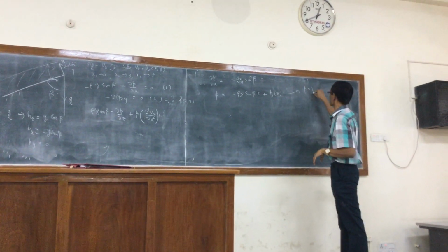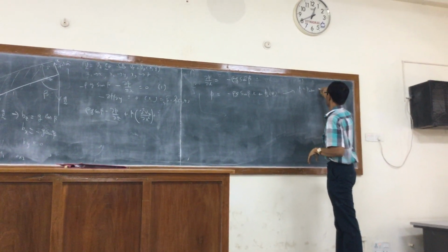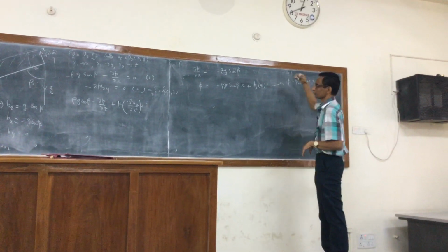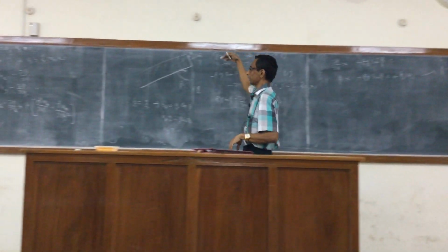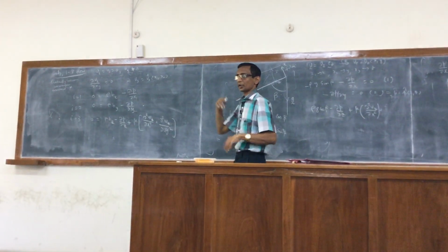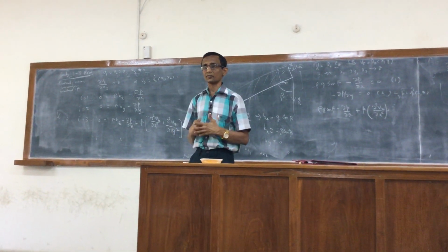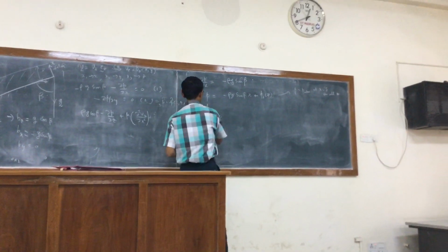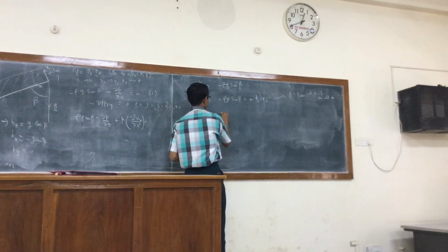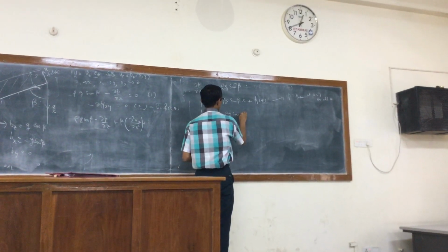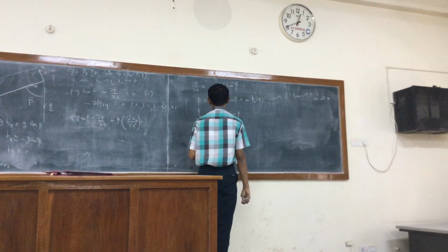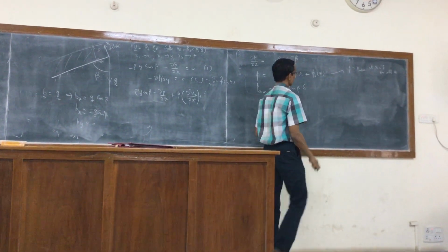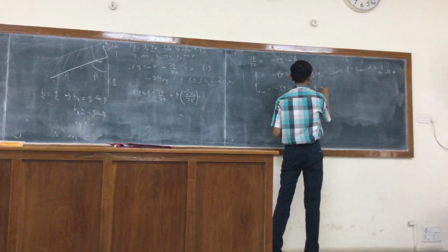The typical boundary condition is that P equals P atmosphere at x equal to delta, for all z. There is a certain height variation, but we assume that the atmospheric pressure is acting uniformly on the surface of the film for all z. And that would mean we get P atmosphere is equal to minus rho g sine theta delta at x equal to delta, that is at the surface of the film, plus P naught of z.